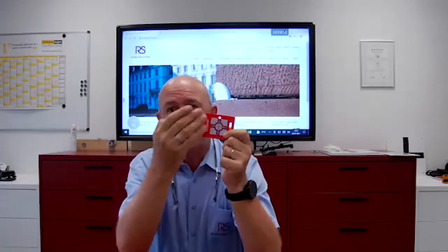Right. Yeah, I would say I'm very, very, let's say, afraid when people do that, because I can show you the reason. With the prism, whatever happens, it takes over the center point. You have the offset, the center point is sure with ATR. In the target reflector mode, the danger is when you are doing this automatically and the target reflector is going dirty, the center is moving because it doesn't recognize the center anymore.